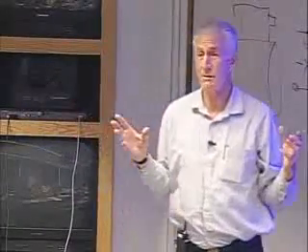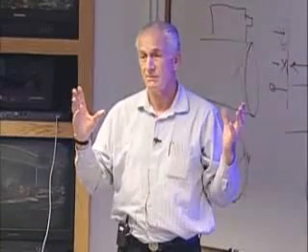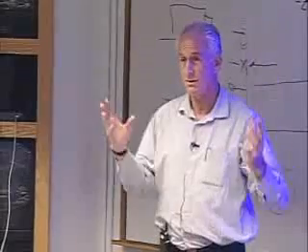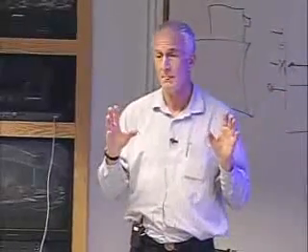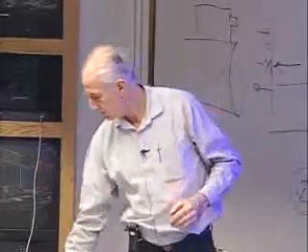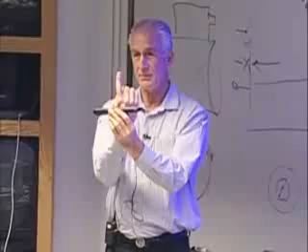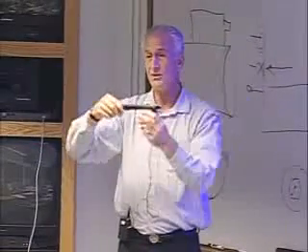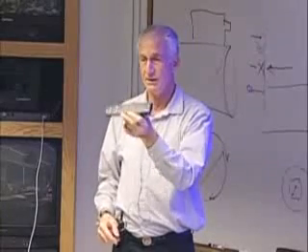So remember we talked about with the primary thrusters, they were designed and sized for rendezvous, where you actually have to have controlled propulsion. And if you want a Z propulsion of the shuttle, you want to be able to get a pure Z. So you fire thrusters on each end, and the same for roll and yaw.